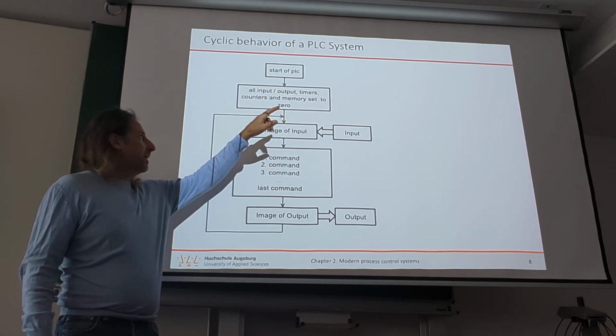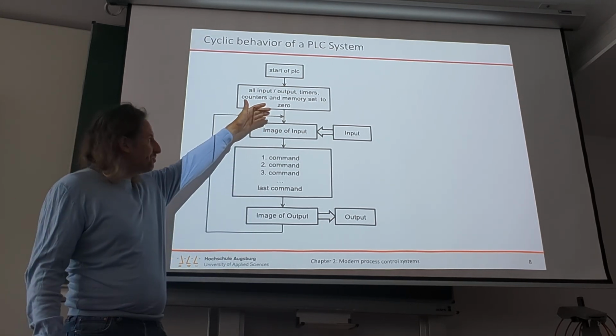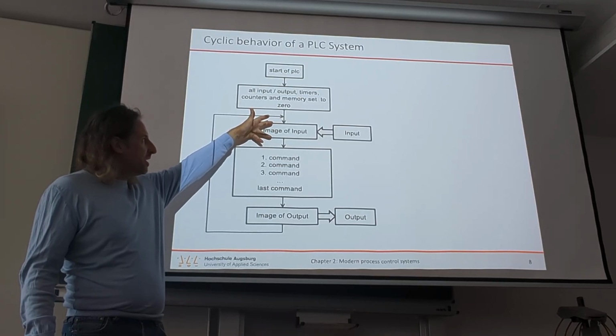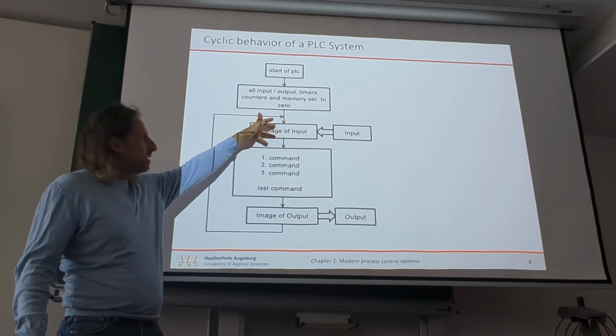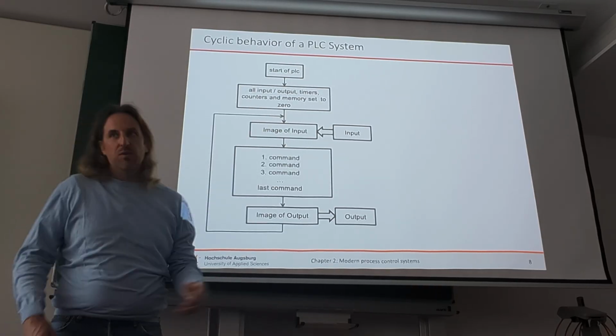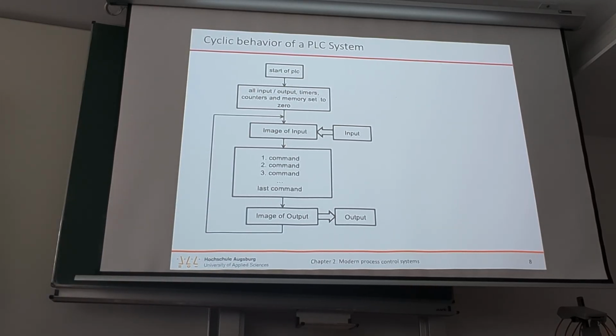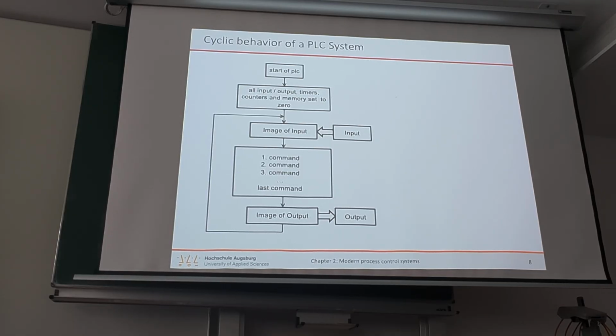That's different. Then we actually start the system, and then we have this image of inputs. The image of inputs is also very different in thinking. When I first worked with an automation system, that was the main challenge for me as an IT guy, because the system at the beginning takes a snapshot of all the inputs that are available and copies that to the image of inputs.